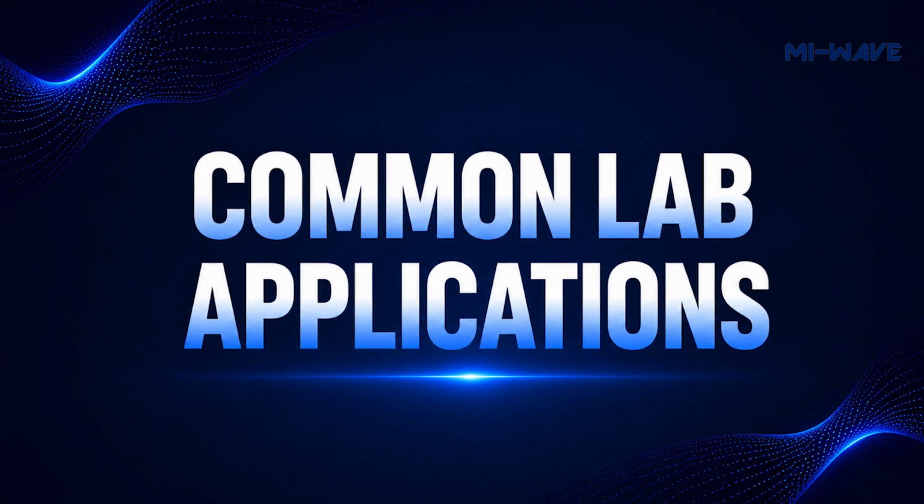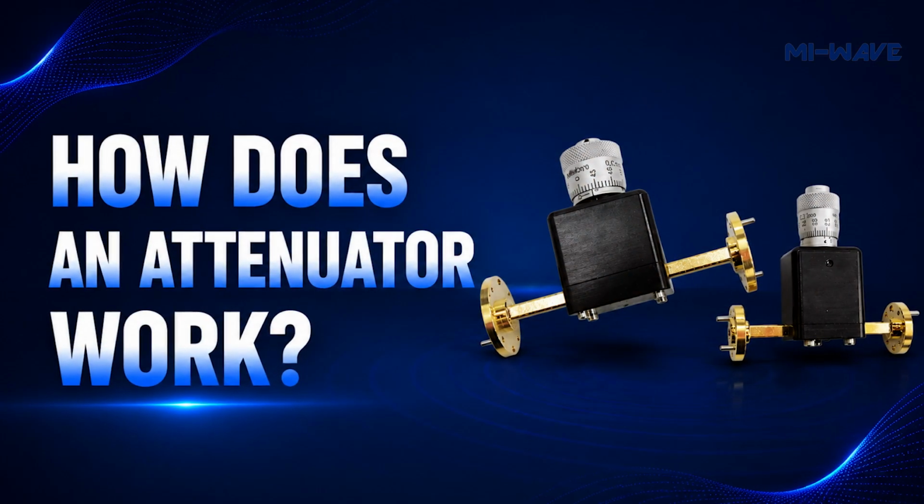Let's look at a common lab application. Suppose you are testing a low noise amplifier. The amplifier output may be too powerful for your spectrum analyzer or measurement receiver. Adding an attenuator between the amplifier and the test equipment protects the instrument and allows accurate measurements. How does an attenuator work? Inside the attenuator, part of the RF energy is absorbed and converted into heat, while the remaining energy passes through to the output. The amount of reduction is specified in decibels or dB.